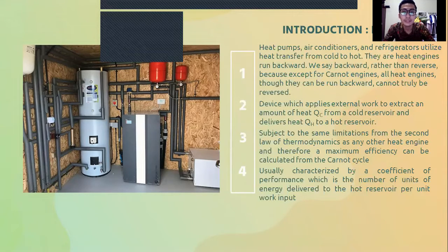A heat pump is a device which applies external work to extract an amount of heat from a cold reservoir and deliver heat to a hot reservoir. It is subject to the same limitation from the second law of thermodynamics as any other heat engine, and therefore the maximum efficiency can be calculated from the Carnot cycle. It is usually characterized by a coefficient of performance, which is the number of units of energy delivered to the hot reservoir per unit work input.